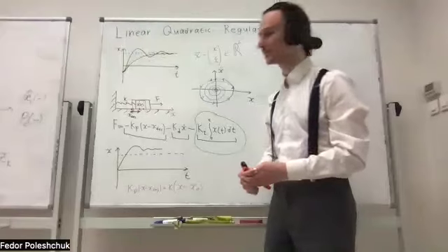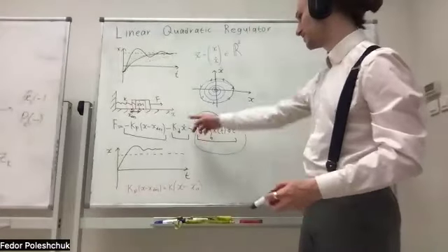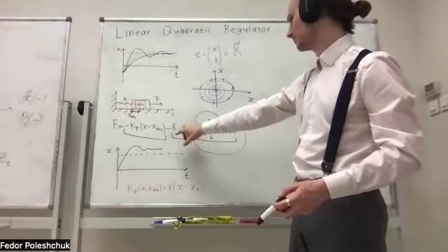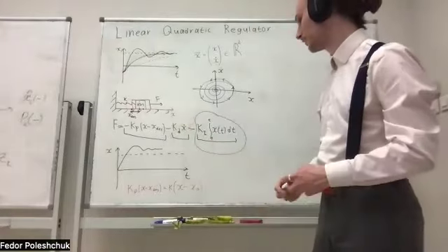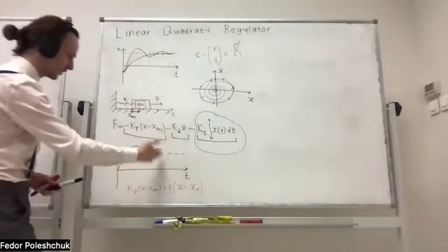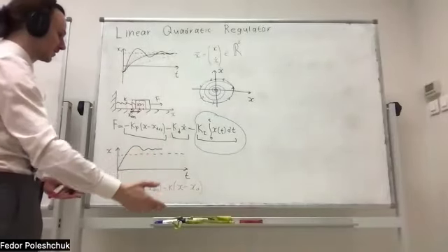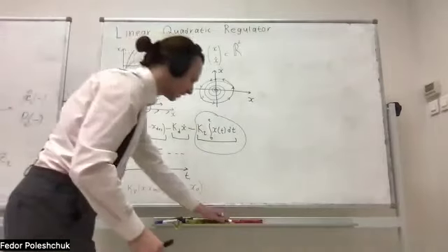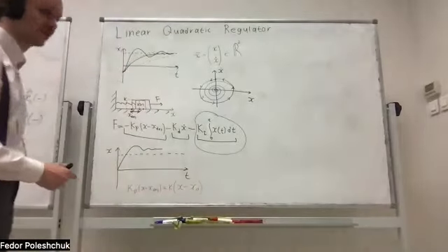Because of that, it'll remain static in the displaced position and not in the desired one. And the speed is zero, so this term is zero as well. And this leads to non-zero deviation in terms of the coordinate that we can't do anything about, except for adding some integral term.